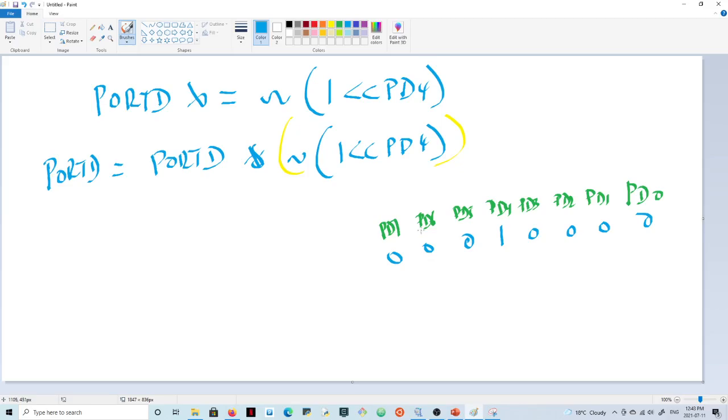Now, when we add the toggle to it, we are knotting it, or we are doing a bitwise NOT here, right? Each bit, because it's a unary operator, is going to become 1, 1, 1, 0, 1, 1, 1, 1. So this whole part here reduces to this here.